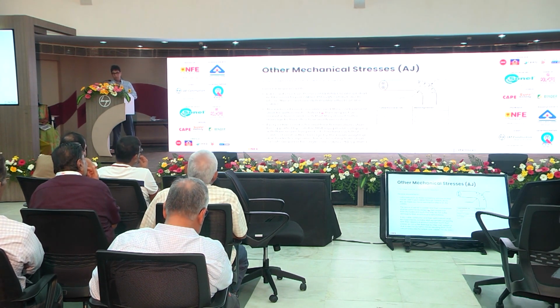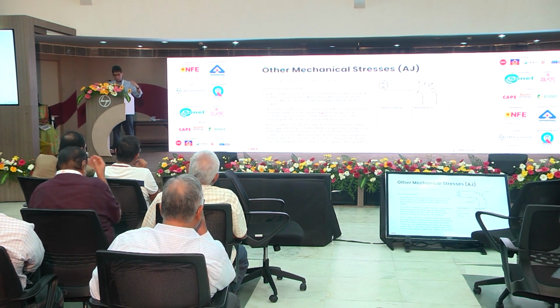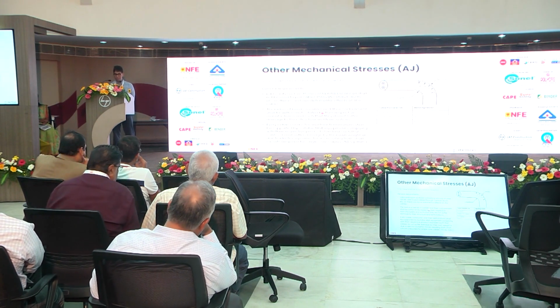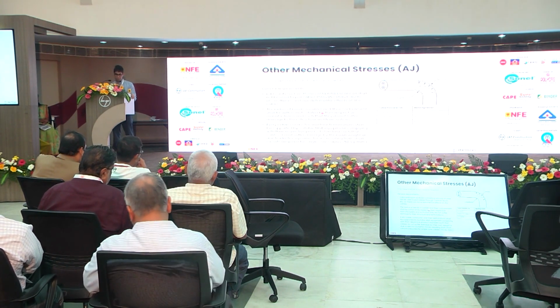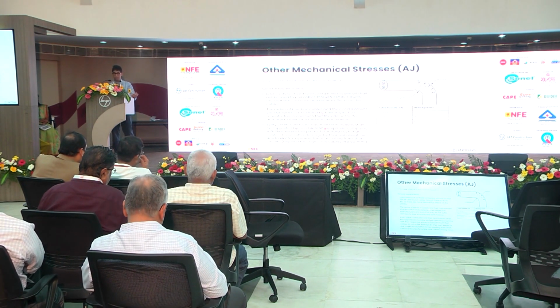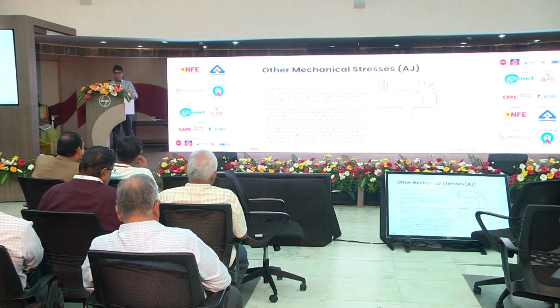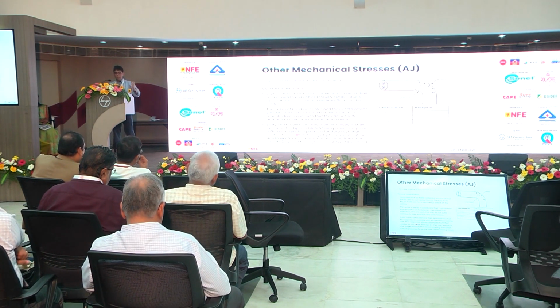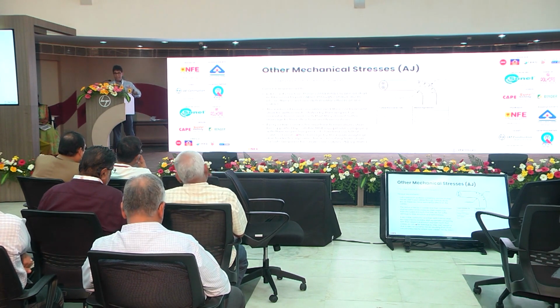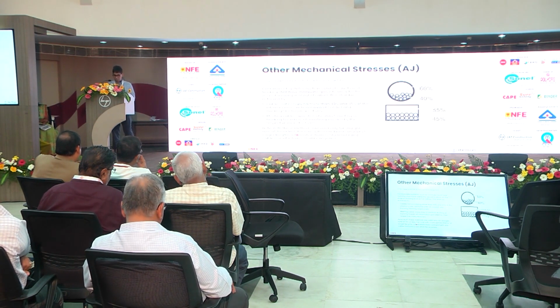Now, every cable, conductor and termination needs to be supported by adequate mechanical and electrical equipment. So usually your M&E manufacturer will do a load calculation for you free of cost. I know Hilti does one. And it needs to be considered that there should be no damage by their own weight. Additionally, if you have single core cables that are greater than 50 square millimeters, depending on some applications, due to a short circuit happening, there are some electrodynamic forces in these conductors, and you can see the mechanical effect of that. So the M&E equipment has to be rated for withstanding that as well.